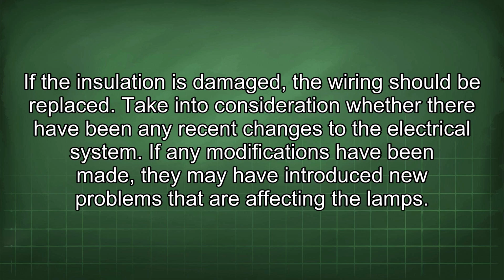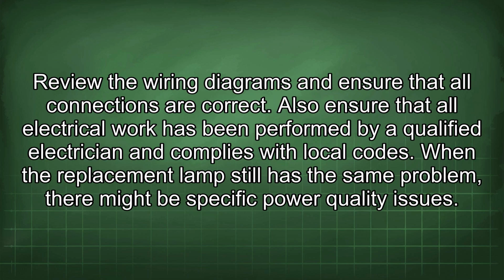Take into consideration whether there have been any recent changes to the electrical system. If any modifications have been made, they may have introduced new problems that are affecting the lamps. Review the wiring diagrams and ensure that all connections are correct. Also ensure that all electrical work has been performed by a qualified electrician and complies with local codes.